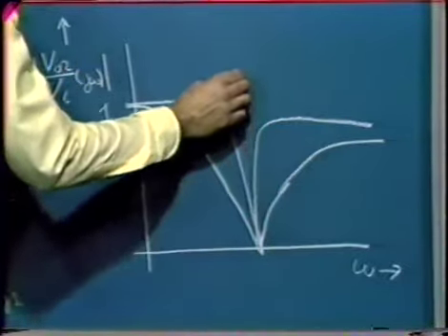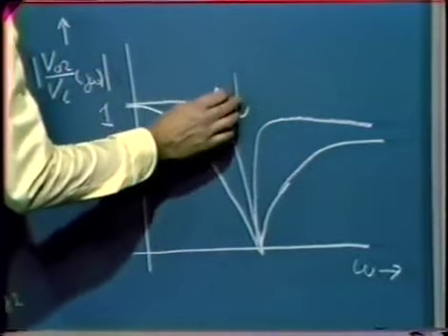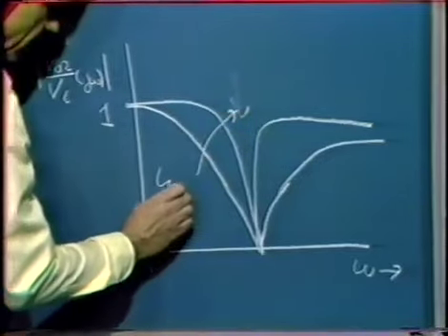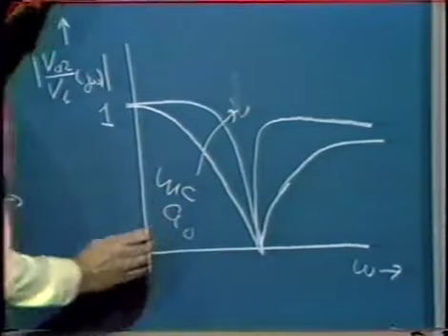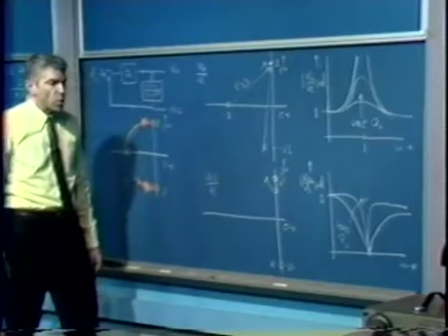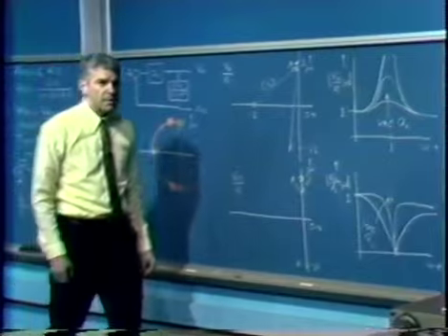So this is the direction of increasing A0. As we increase A0, there becomes a narrower and narrower band of frequencies that we reject. We can build a very, very high quality rejection amplifier using that technique.